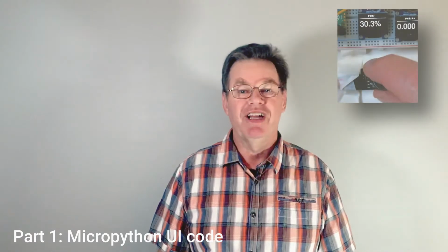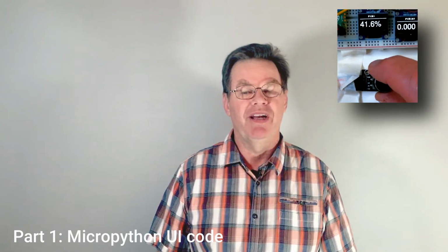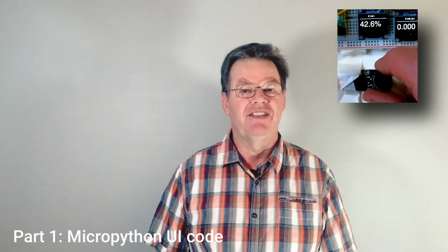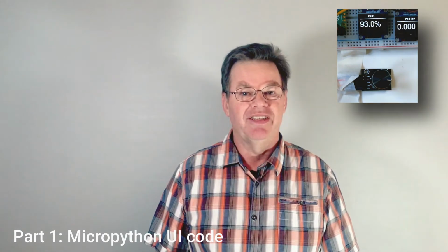And I'm going to do this in 3 parts. Like I said, this first part is going to be about MicroPython and the UI to be able to control each of the rotary encoders and display the results on an OLED in a nicely formatted way. I want to define the class to do that for one rotary and OLED combination. Then I need 4 of those, so I can just roll it out 4 times to use the class for the 4 input parameters.